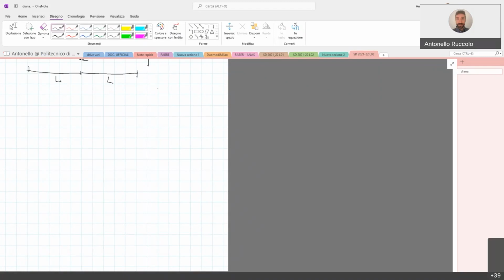And then we study the effects in terms of moments and forces acting on the node that we are restraining. And we impose equilibrium equations in those nodes so that we can find the actual values of displacement or rotations that ensure equilibrium in those nodes. So, also similarly to the first method, we can use the superposition principle.